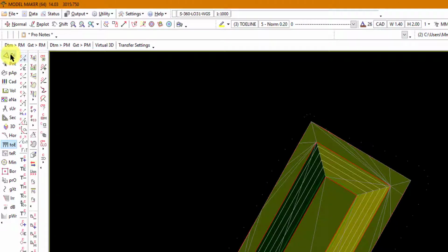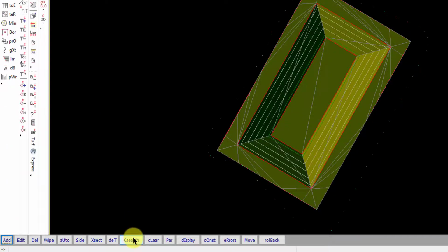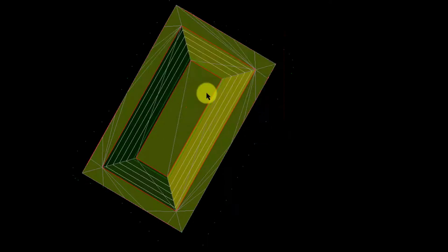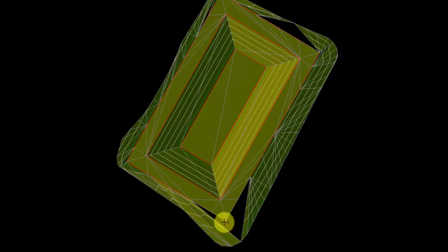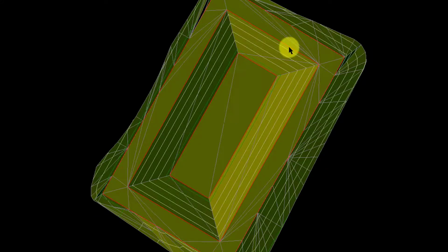And if we then go to triangles and we say C search, continue search, the triangles are generated. Now I can see some of the triangles were not created, but that's because of triangulation rules. But I will manually add them now using triangle add shortcuts. And I'll just fill the gaps manually here. Now these triangle parameters you can set up in the triangle menu under the parameters for triangles. But that's another topic for another day.